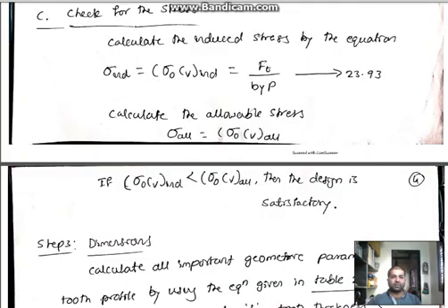Step 3. Check for the stress. First we calculate the induced stress. Then we calculate the allowable stress. If induced stress is less than the allowable stress, then the design is safe.